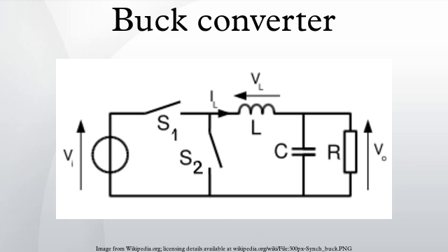When the switch is opened again, the voltage source will be removed from the circuit, and the current will decrease. The changing current will produce a change in voltage across the inductor, now aiding the source voltage. The stored energy in the inductor's magnetic field supports current flow through the load. During this time, the inductor is discharging its stored energy into the rest of the circuit. If the switch is closed again before the inductor fully discharges, the voltage at the load will always be greater than zero.